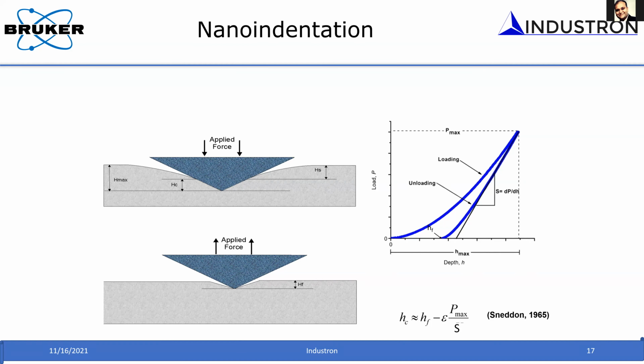Geometry. While if you take the same copper, work harden it, and create a large amount of dislocation density, and then you do an indent, the same copper will behave differently. It will have a totally different deformation, in which case there's no room for the material to get accommodated. It will pile up to the surface. So even with the same copper, depending upon the state, whether it is well annealed or work hardened, you will have two different kinds of response.